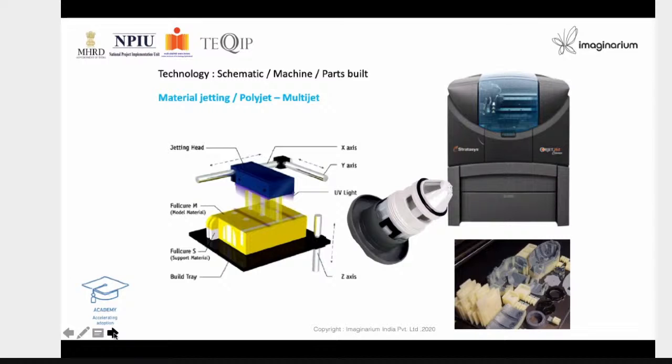Moving forward, we have yet another great technology, that is material jetting. So here, instead of binder jetting or glue jetting, the material itself is put on the substratum. So how do they do that? They use a piezoelectric hammer by which a photosensitive paste-like material is deposited by a large printhead, because of which you can do things which are pre-assembled, hard and soft, transparent to opaque. That kind of variety you can bring within the same part.